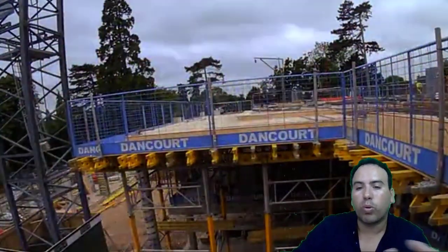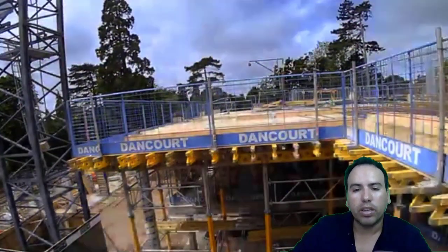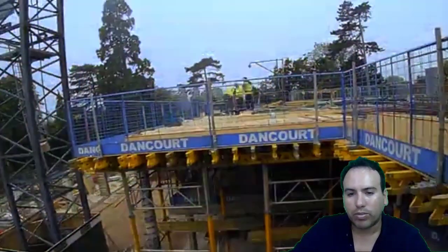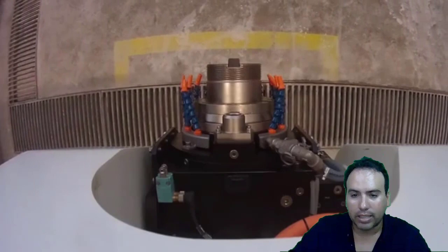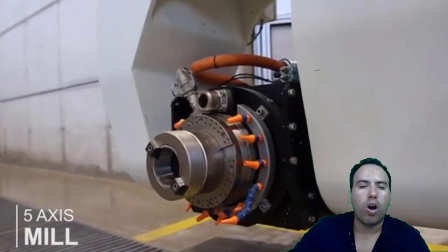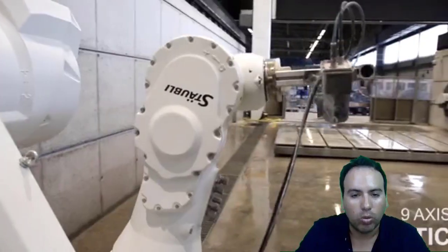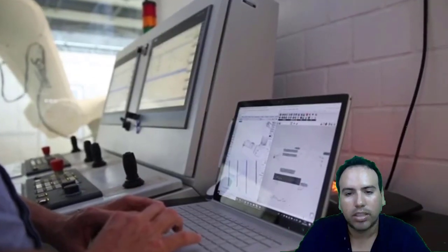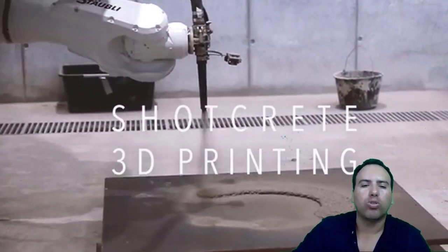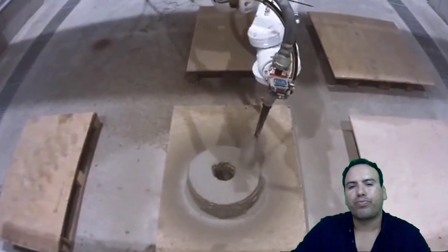Since the columns are supported by the foundation, the load from all components is relocated to the columns. Then it will be transferred from the column to the footing adjacent to it in the form of axial force. Moreover, columns transfer lateral loads to the foundation as well as such loads imposed. Lastly, it will transfer the moment and shear also to the footings.